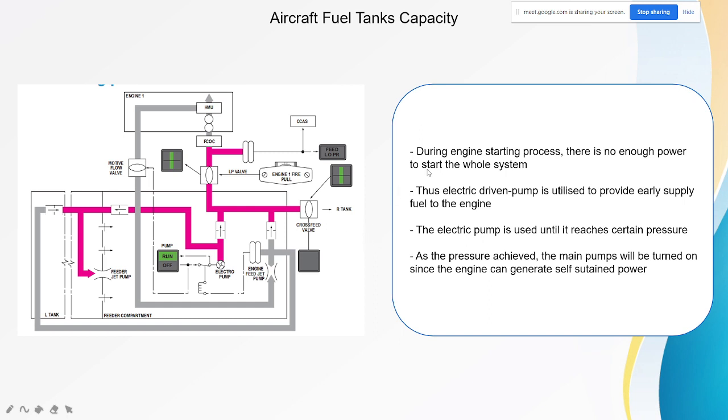During the engine starting process, there is not enough power to start the whole system. So fuel is supplied to the engine through the electric driven pump here, driven by electric power from the battery, which is utilized to provide an early supply of fuel to the engine.